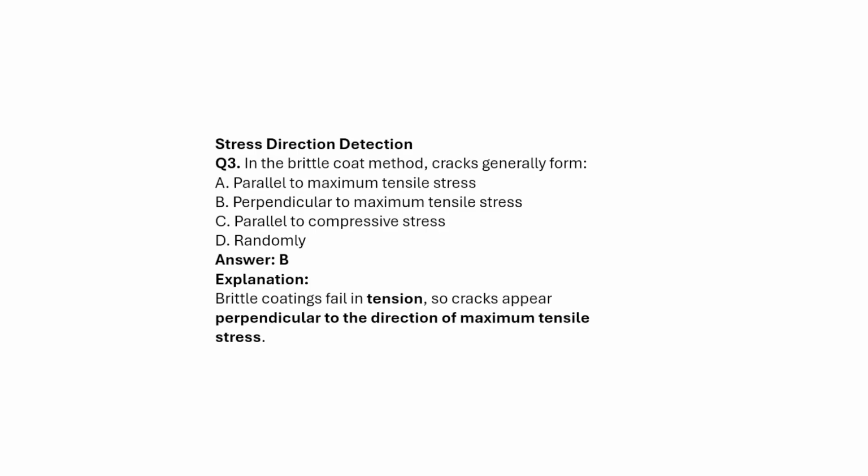Okay. In the brittle coating method, the cracks generally form: parallel to the maximum tensile stress, perpendicular to the maximum tensile stress, parallel to the compressive stress, or randomly. Answer will be perpendicular to the maximum tensile stress. The brittle coating fails in tension, so the cracks appear perpendicular to the direction of the maximum tensile stresses.